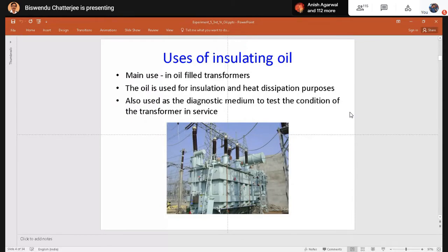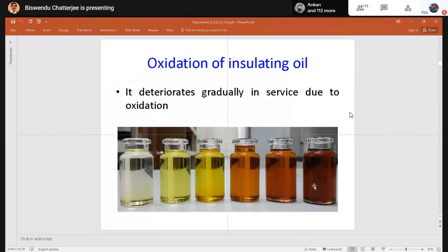You take a little oil from the drain valve and find the oil is like the right hand side. Now what will be your inference? Yes, the transformer oil is not in good shape and it will affect the overall transformer performance. That is why you need to know the physical appearance of the oil. In the lab, we are not in a position to show you practically now, but if you come to the lab later, we can show you a good and a bad transformer oil.